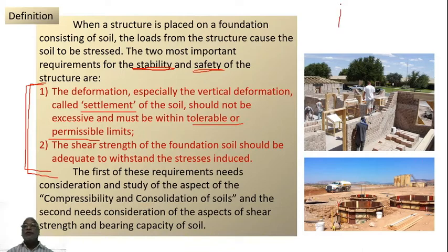Suppose this is a building and this is the ground level. There is a layer of soil on which the foundation is laid. Now this structure is going down, in the sense the whole of this material is not going down. Somewhere there will be an incompressible layer. This layer of soil is getting compressed. Whatever it may be, around 5 meter or 6 meter or 2 meter layer of soil, because of the heavy load of the structure, it is getting squeezed or compressed.